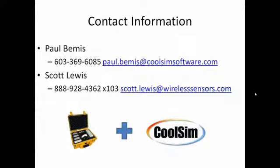It says here, why are we only using rack cooling units? What is the source of the outside air as required by the mechanical code? Not sure. These data centers are self-contained systems, so the air stays in the room. They're closed loop. They come out of the racks, and then they go back into the cooling units, and then back out of the cooling units into the racks. The other question? The room actually did have some other cooling capability outside of just room cooling capability, so that's where external air would have been available. Those units were turned off for these tests, and I suspect they're turned off more often than not. Yep.